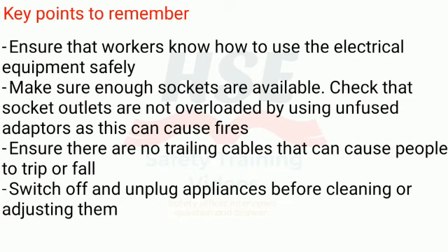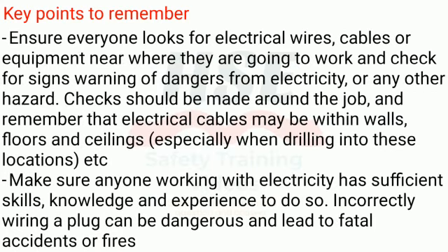Switch off and unplug appliances before cleaning or adjusting them. Ensure everyone looks for electrical wires, cables or equipment near where they are going to work, and check for signs warning of dangers from electricity, or any other hazard. Checks should be made around the job, and remember that electrical cables may be within walls, floors and ceilings, especially when drilling into these locations.